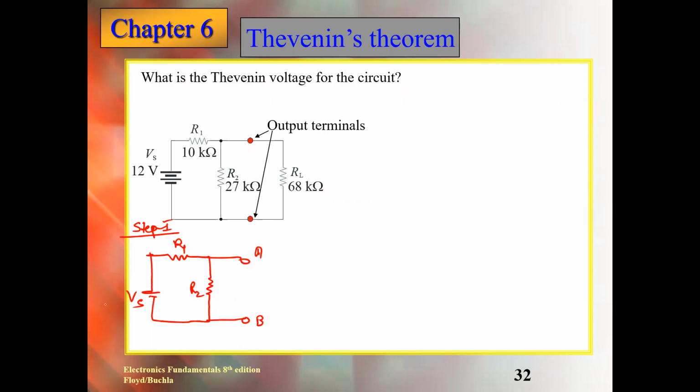Now guys, what is the second step? Calculate voltage VTH, which is basically VAB, or VR2. Okay, how much will it be? Can we calculate easily?